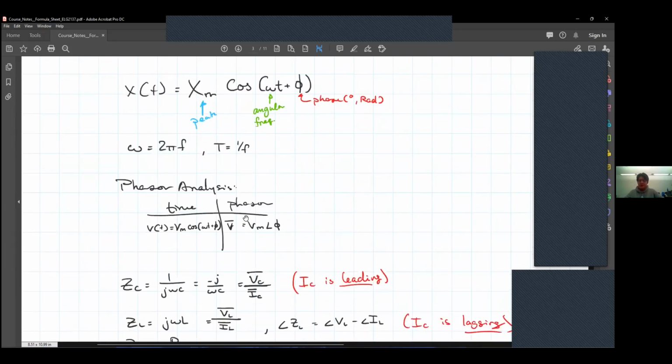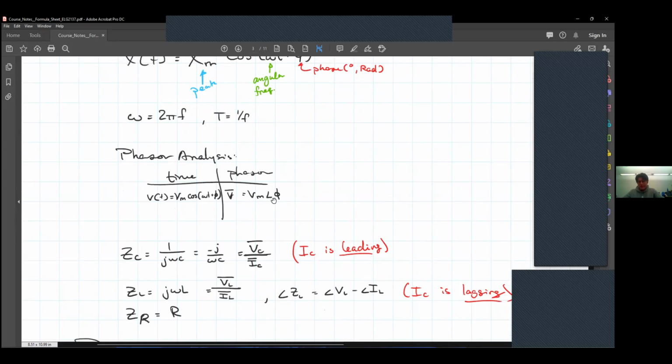And you can actually convert this to a phasor value, a phasor being a vector in the time axis, if that's easier to understand. Basically, a way to think about this is if you have a sinusoidal function moving through time at a certain rate, certain frequency, you kind of ignore the frequency when talking about phasors. You just assume everything has the same frequency if you're working in phasors. And then you just talk about the phase shift. So you talk about voltage having a certain magnitude heading in a certain direction in time, which is the phase shift.